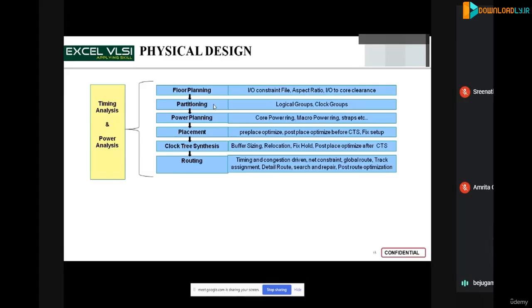So at every stage, parallelly from placement, an optimization stage is introduced where we do some manipulations to optimize these 3 parameters. So this completely is the physical design flow. We are introducing that module also for the internships, and this is basically done in a tool called Innovus in Cadence. And yeah, is it clear till now?